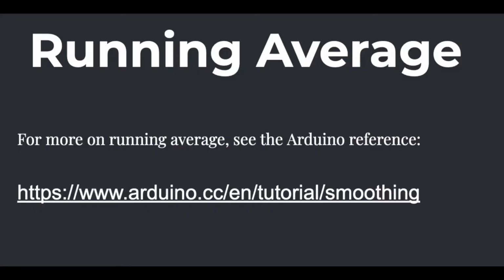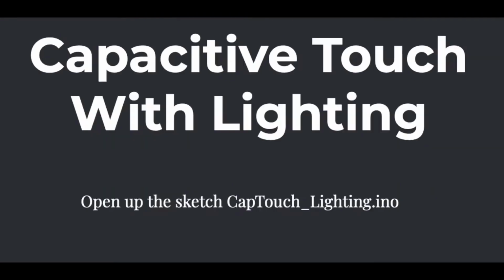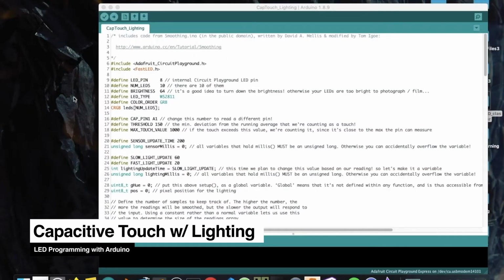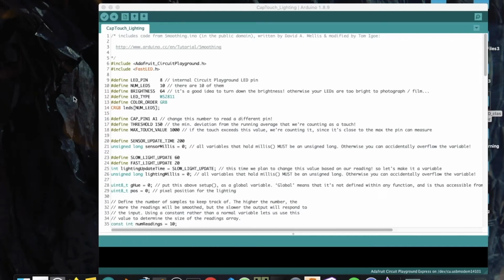I added a special check for whether the value read is close to the max touch value, since that's where the running average of a long touch will tend to congregate. To learn more about smoothing and running averages, see the Arduino reference below. Now it's time to add in our lighting interactivity. Open up the sketch CapTouch Lighting. In the sketch CapTouch Lighting, we'll be controlling lighting using our CapTouch data.